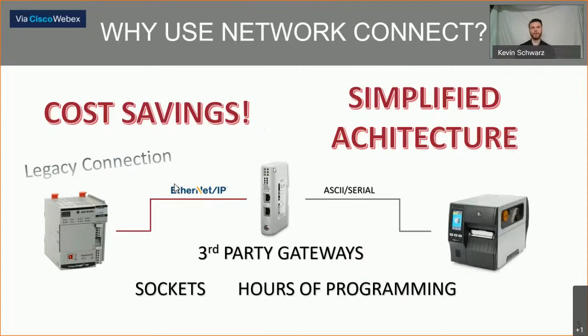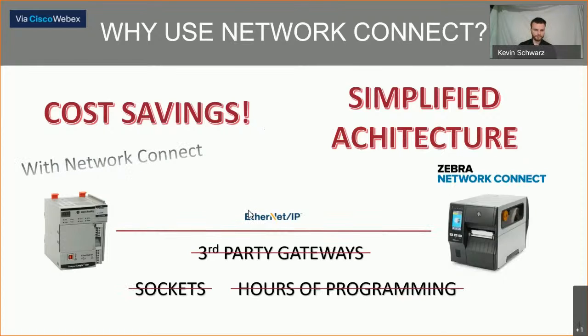The other way of being able to communicate with these in the past is that you would write your own sockets going from the PLC to the printer via Ethernet. And that too would require hours of programming, additional logic to be developed, and ultimately a lot of time and energy invested into getting your printer to print from the PLC. So with NetworkConnect, we now can go straight from the PLC to the printer without using any socket communications, directly over Ethernet IP.